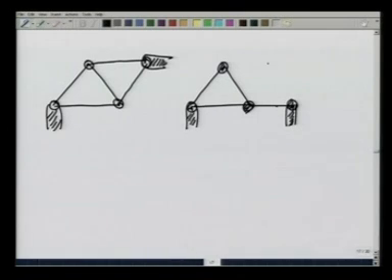So, I have to provide one more member, so that there are 3 forces acting on it. But this gives a loose end here. I could fix this loose end by putting 2 members here. Now, you see each joint has a minimum of 3 members, so that this becomes a statically determinate structure.